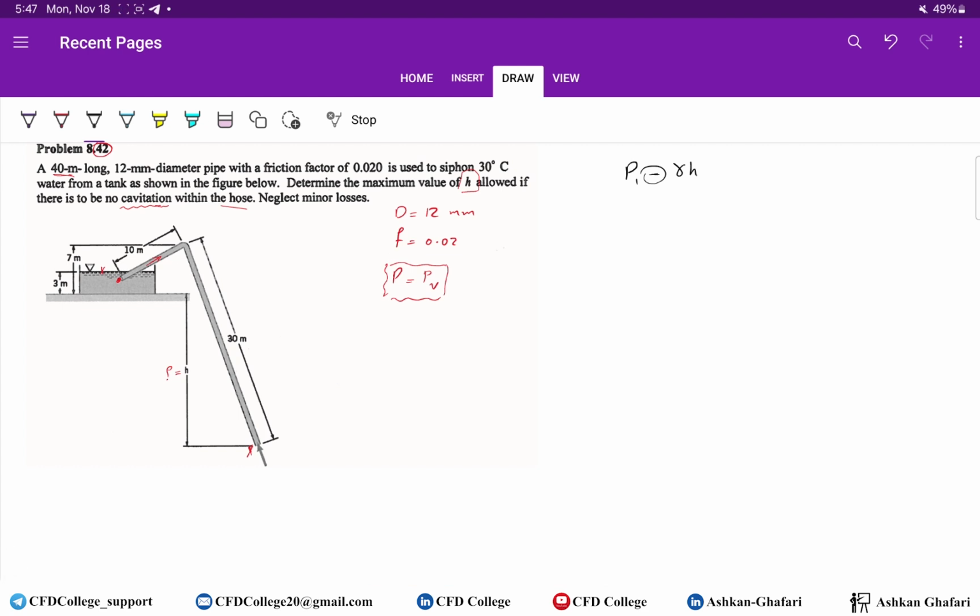In other words, you have to overcome the potential energy, because this point, with higher elevation, has more potential energy, so you have to overcome this. And it happens when the pressure turns into potential energy, and that's the reason why pressure is decreasing as you are moving upward.